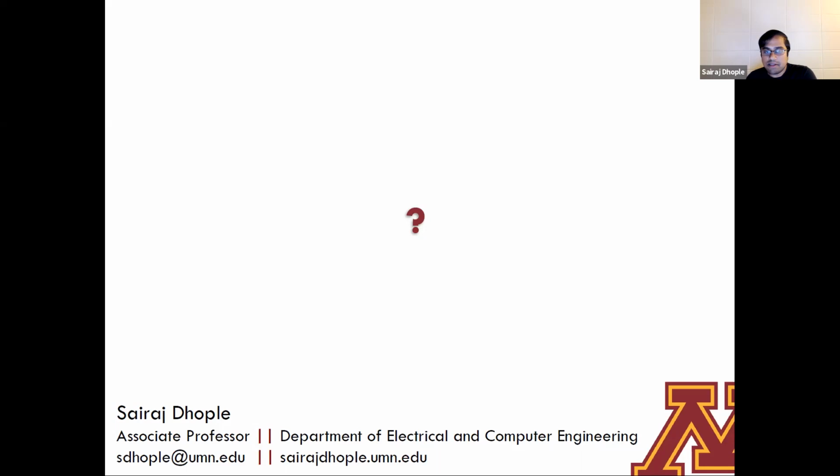Again, good question. We have not used anything super fancy here. This was all TI digital signal controllers, and that was very well suited for the particular application. We didn't use any FPGAs or anything fancier than that. There are implementation issues, of course. There are a few practical challenges that you will come across, as with any implementation of this sort. I can't think of any that suggest that you need a very fancy microcontroller. So you can just get away with any microcontroller that you're using for inverter control applications. The ones that we used were mostly TI systems.